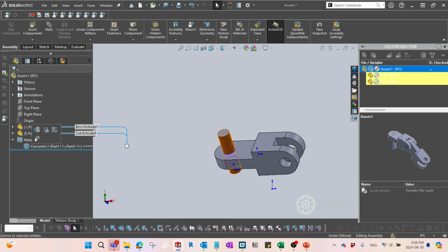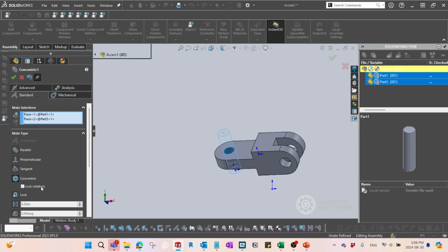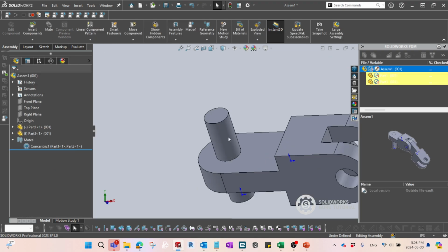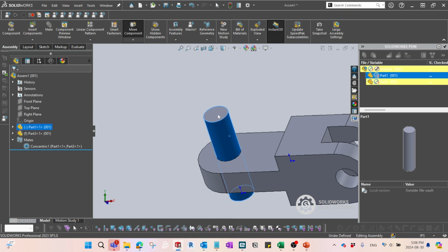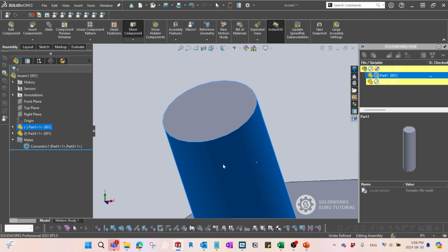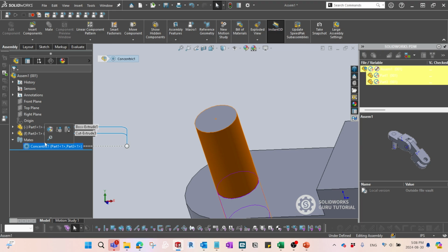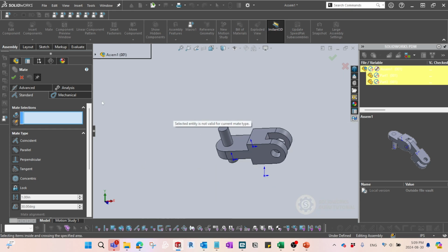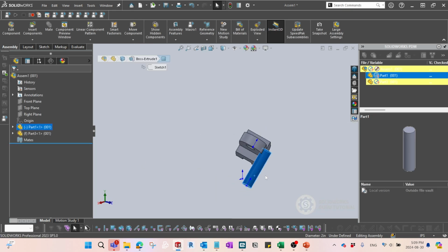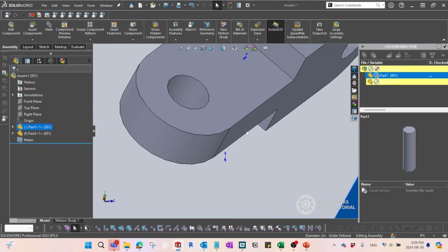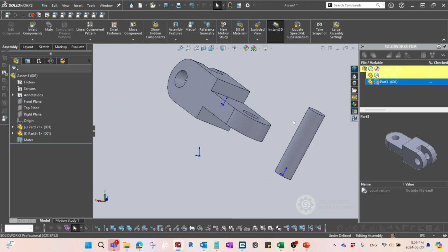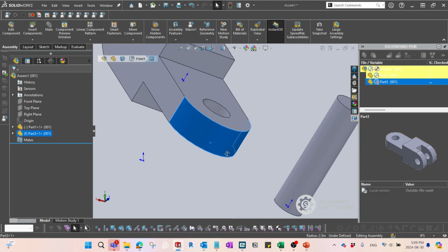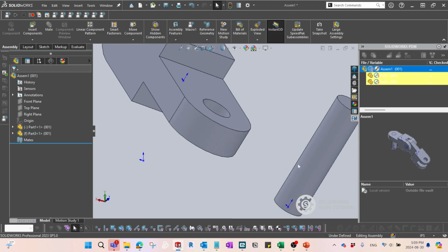But if you go to the edit feature for this concentric, and then check the lock rotation checkbox, and then let's just get out, and then right click and try to rotate it. It's not rotating, it's just going up and down only, because we locked it. All right, that's good. And then let's go to the tangent relation. So the tangent relation would be good to apply when there's a cylinder curve face, and also this kind of dimension, or it could also be concentric to the other arc, or other concentric kind of area.